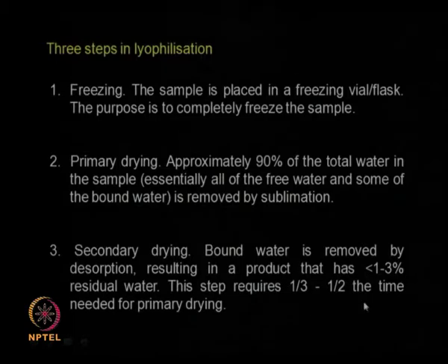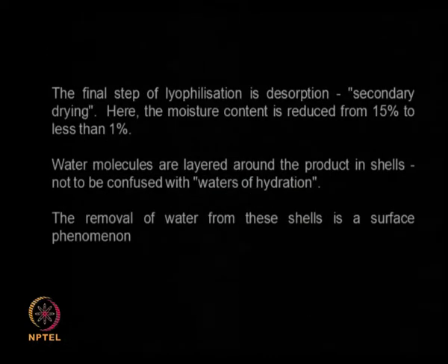This step also takes some time; almost 50% of the time is taken for removing the unbound water, so you need some time for that. The final step of lyophilization we call desorption, or secondary drying, or drying to remove the bound water, so you reduce the moisture content to almost 1%.